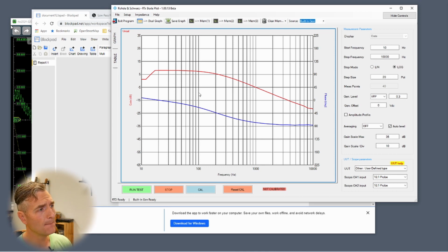And that mostly sits around 150 hertz and below. And I don't really want anything above 150 hertz going into my subwoofer. So the steeper the slope, the fewer high frequencies make it into the subwoofer, and the subwoofer should sound better. So in order to increase this slope, to make this line steeper, using passive filters, I can string together more R's and more C's.